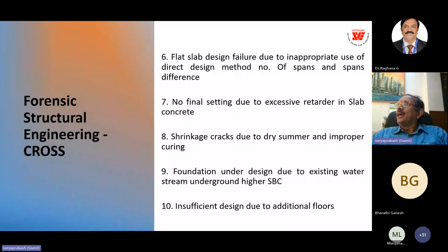And no final setting due to excessive retarder. In concrete mix design, we use retarder nowadays, particularly in ready-mix concrete. When we add retarder to ready-mix concrete, excess retarder will delay the setting, and too much excess retarder will delay initial setting even beyond 36 hours. And shrinkage cracks due to dry summer and improper curing. Many times we come across these, and we restore them.